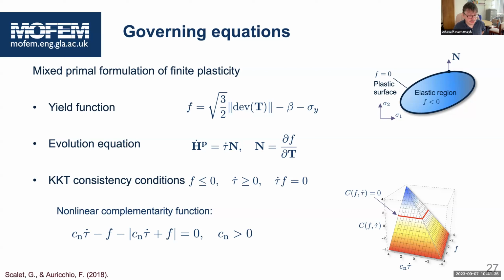So then you don't have quadratic convergence for your Newton solver, but when you start to be close, you retrieve the quadratic convergence to your equilibrium. But that is exactly the case when you run the plasticity in the classical way.